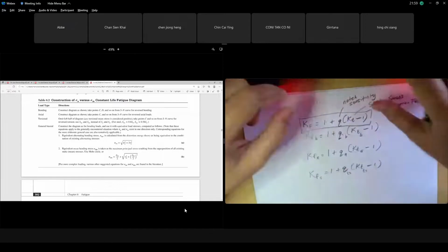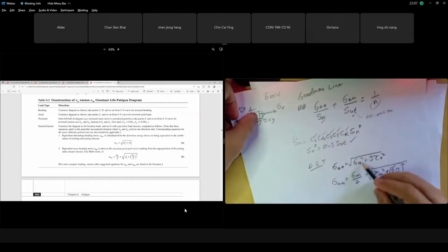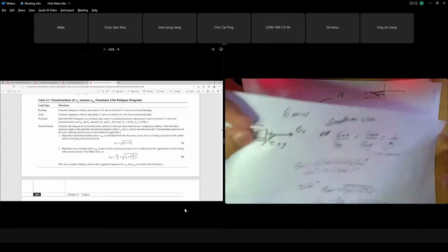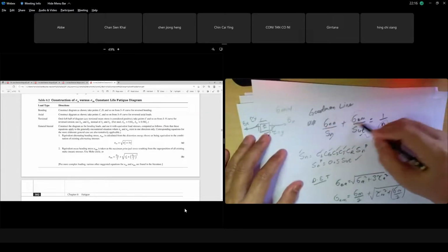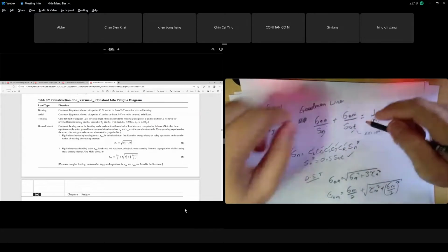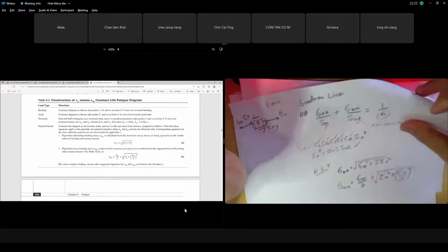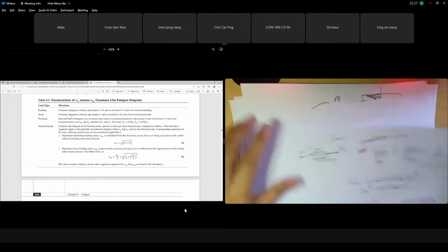This Kf has to be multiplied to all your stress. Then your stress will be substituted into your equation for sigma a, what is the amplitude, what is the mean. That stress will be put into this to calculate your safety factor. Alright, if you still do not understand what I'm talking about, let's go to this sample case.